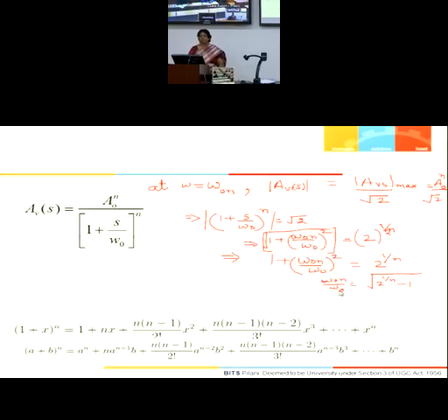Suppose you are given omega unity. So I can express omega naught n in terms of omega unity also, or UGB also. Unity gain bandwidth. How will you rewrite it? Because omega naught will be omega unity divided by the gain of every stage. Remember, for a single pole transfer function, UGB is equal to gain times 3 dB. So I am using that expression.